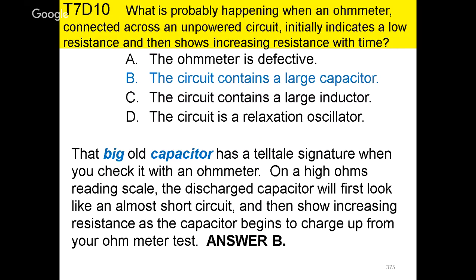A capacitor has some kind of capacity to hold a voltage. Good, well-designed circuits will have a bleeder resistor so that when you power off your equipment, the capacitor will discharge and not hold that potential within it, which can sometimes cause you a little bit of a shock as well.